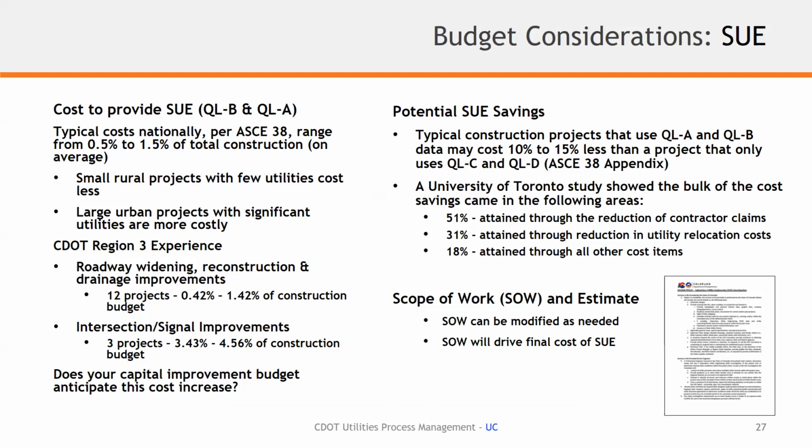because you spend the time looking at the data early, good SUE information allows designers to make some adjustments on their side, mitigate some of the long relocation projects and more invasive types of projects that cost us time and money that we're on the hook for, and then all other costs.